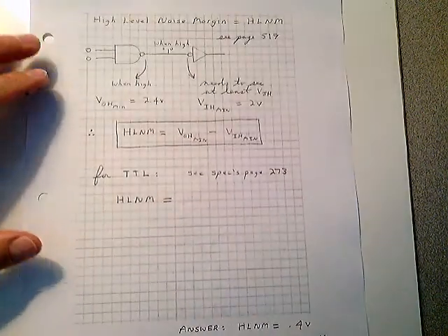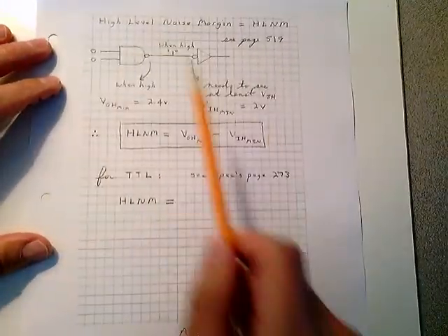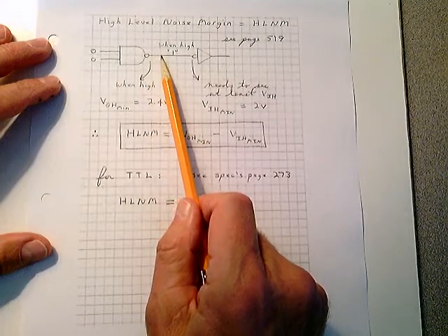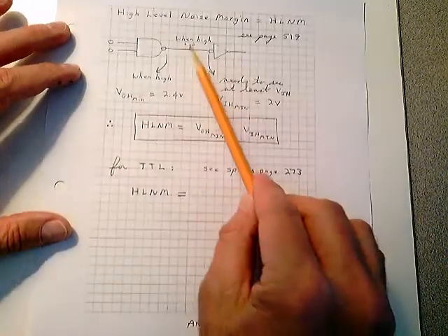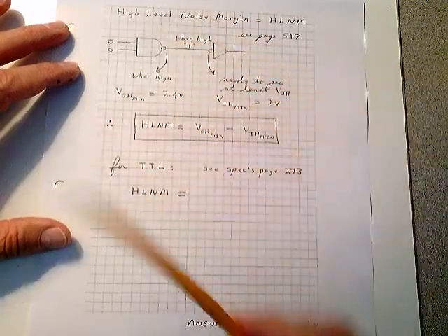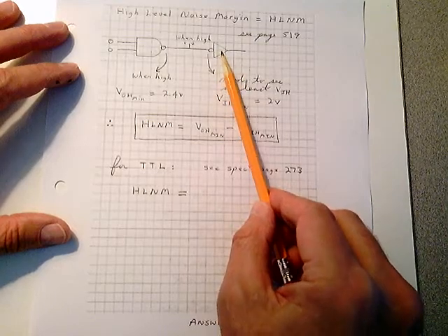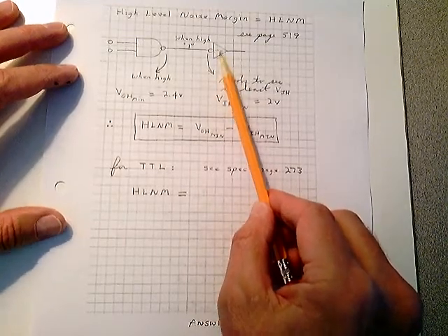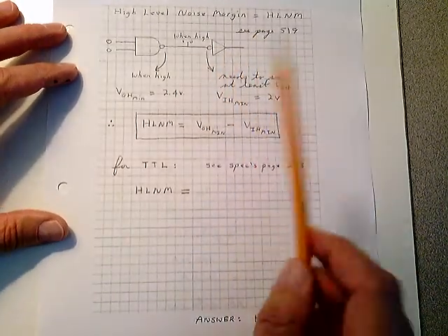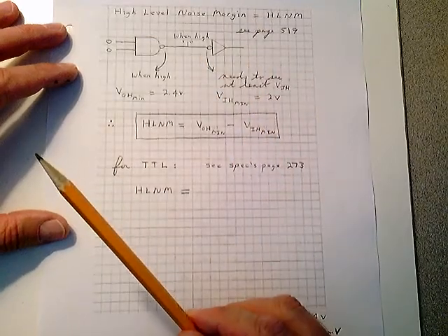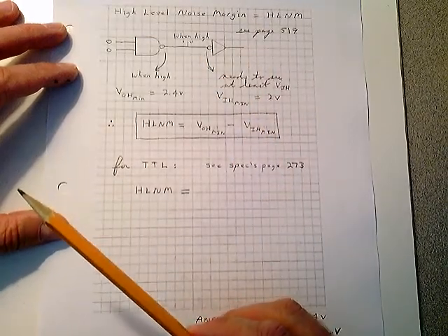And then finally, if you look at page 137, what about the high-level noise margin? In the high state, when you're expecting 5 volts, we know there's going to be noise riding on that 5 volts, dragging it lower. How much can you tolerate before this gets confused, before it drops down into that invalid region that I showed you in that graph a minute ago?